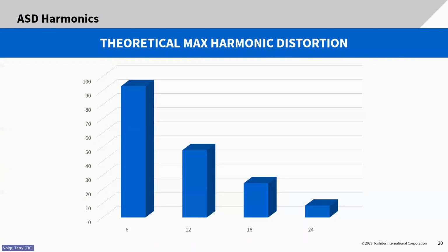So if you have 1,000 horsepower worth of power, but you're using a 1 horsepower 6 pulse drive, you're not really going to make a huge impact on the entire harmonic spectrum. But if you're using a 900 horsepower drive and 1,000 horsepower total, you're definitely going to see some of those effects.